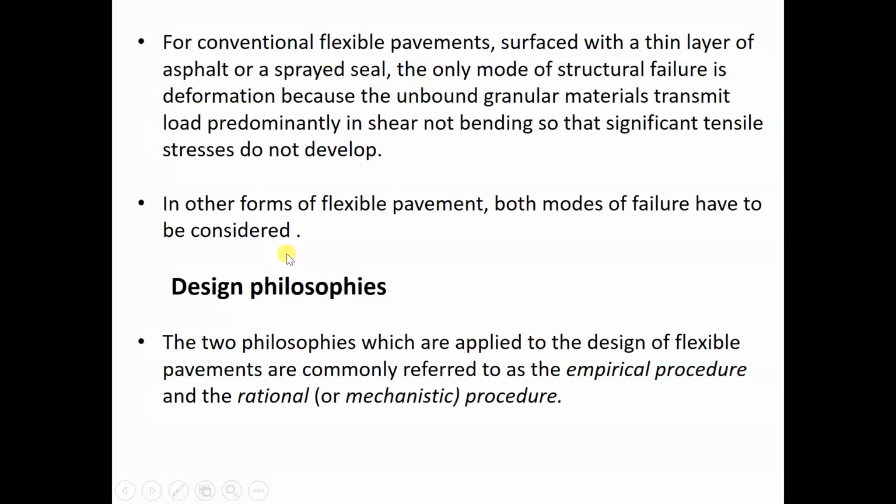So we have to consider both the cracking as well as the deformations, because whatever type of pavement, whether bound or unbound, the subgrade usually exhibits some sinking, the deformations. So we always still have to consider the deformation of the subgrade for all types of pavement.